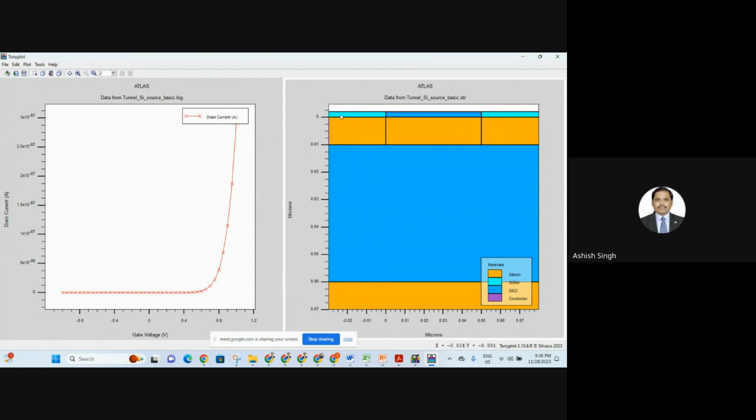If you do not define this, it will not be rectangular, because a zigzag will occur: gap, then oxide, then gap. This is not rectangular. So to make it rectangular, we have to define some value. Actually this is air, so we have to define air as well.